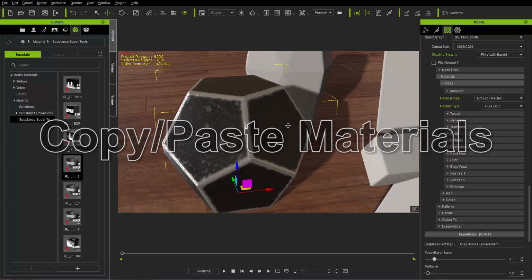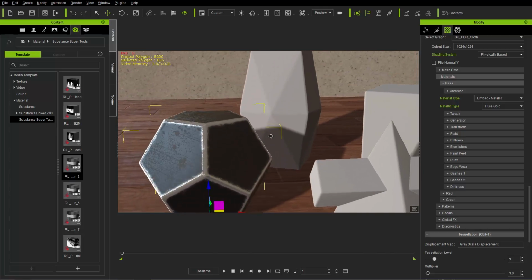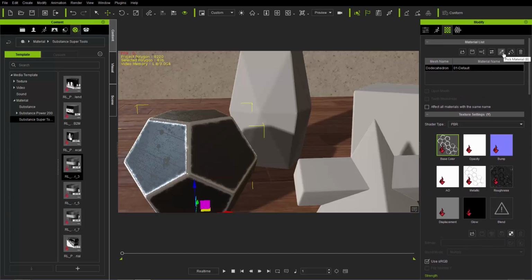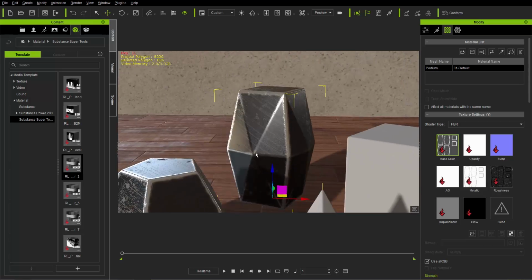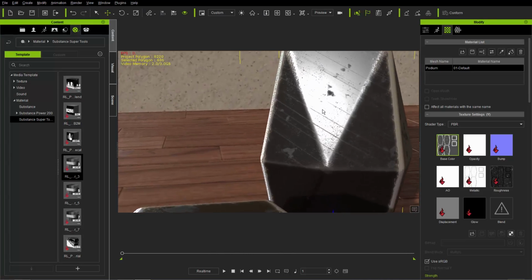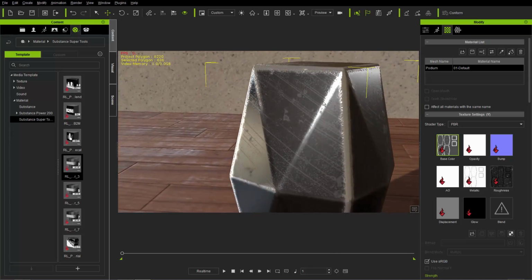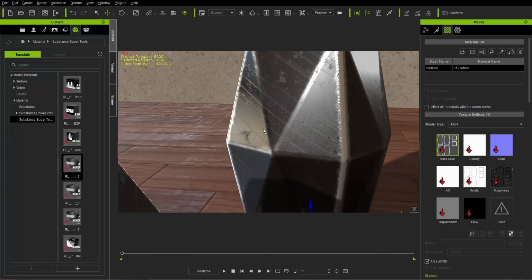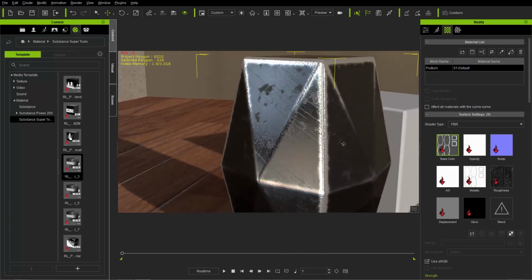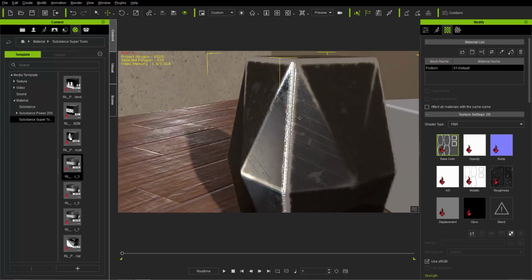Okay, let's go ahead and quickly throw in another one here. The reason I'm going to do this is because if we use this eyedropper tool here, we can also use the B hotkey and select our material. We can then paint it onto our podium right here. There you go. Now we have the podium, and notice that because we have that curvature map, the edge wear is now in the correct places on this podium as well. So we don't have it in a dodecahedron pattern. It knows exactly where to place the abrasion along the edges.